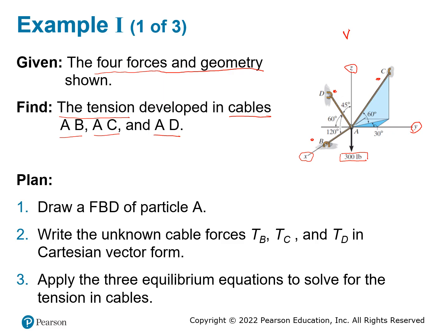And that's important. Now, drawing the free body diagram is going to be the first step. In this case, it's very, very easy because it already tells you what the forces are, and we are analyzing point A. So you focus on point A. When we cut this cable, we know we are going to have a tension force along this cable, in the same direction as this cable.